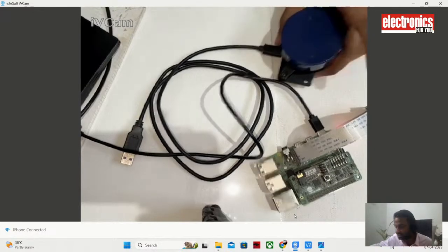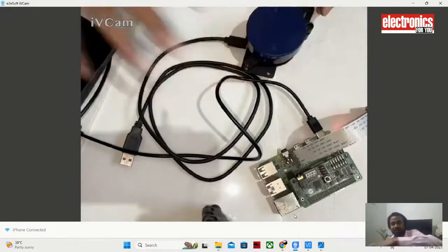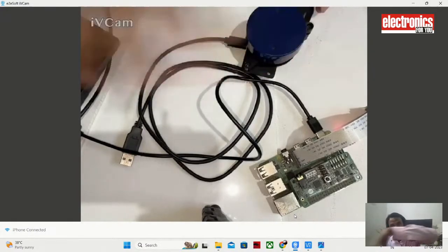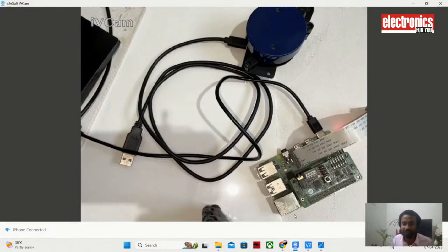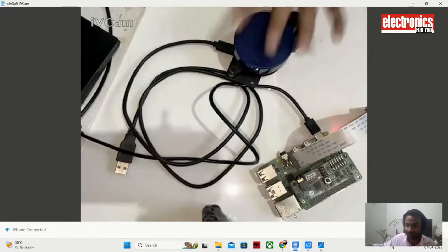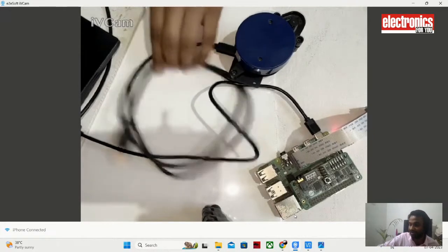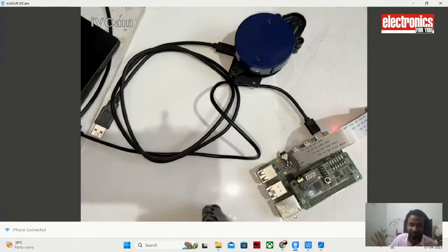but it's better to use the 360-degree lidar because it scans the surroundings to 360 degrees all around your vehicle. So you can make a protection system around the whole vehicle. You can scan all the surroundings of the vehicle, and if any vehicle comes so close to your vehicle that it might cause an accident, it will alert you, and you can see that data in your ADAS system, and it will assist you in parking and many other things as well, and it will also make an autonomous system for that. So we are using this.